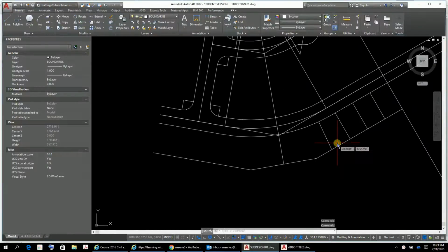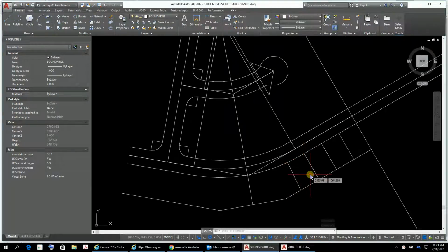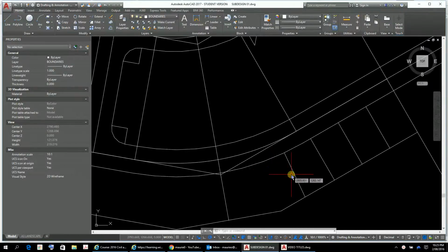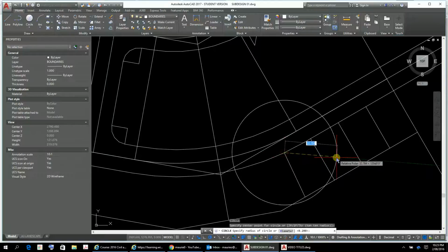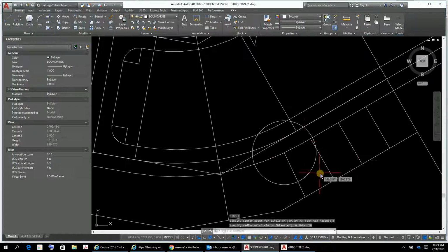Now, since I left you last, I have reconsidered the area of this lot here, and I've adjusted it slightly, so whereas previously it was 595, it's now 602. So what I want to do now is get a 600 lot adjoining that in there. So I'm just going to see how we go. I'm going to go with a 20 meter approximate frontage. So I'm just going to draw a little circle in there with a 20 meter radius. Okay, and use that as my starting point.